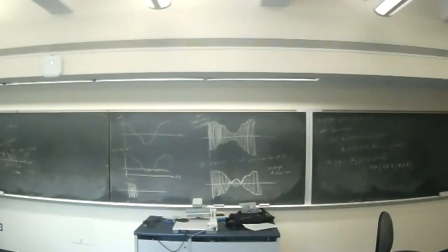It could be 5,000, right? Half the spacing between the radio stations: this could be 5,000, that could be 5,000, but my radio stations are 10 kilohertz apart. Okay. So I'm limited here in that my bandwidth can't be more than half my frequency spacing, or half my channel spacing. Actually, AM radio, they did the opposite.